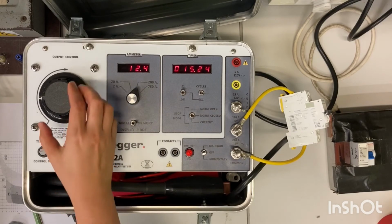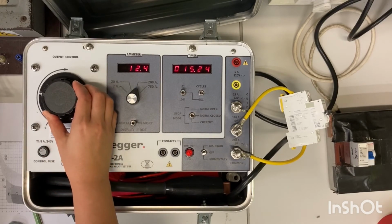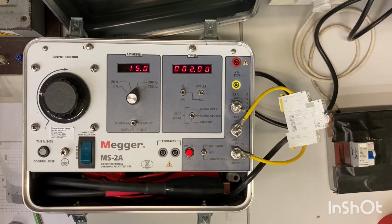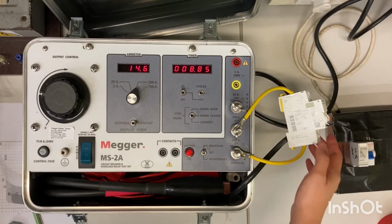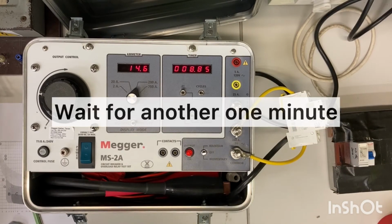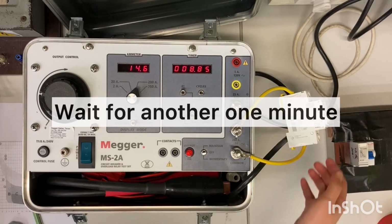And for larger current values, the disconnection time would be shorter and shorter. So for a current value of 14.6 amp, the disconnection time is around 8 to 9 seconds.